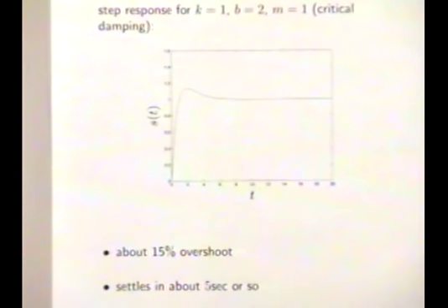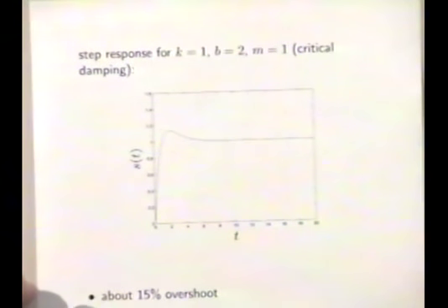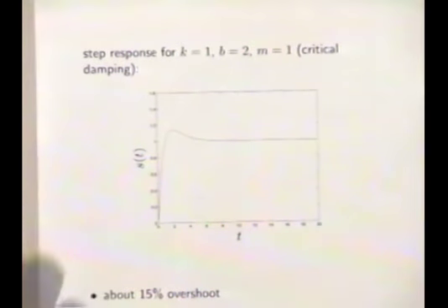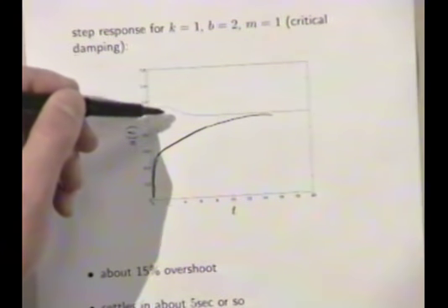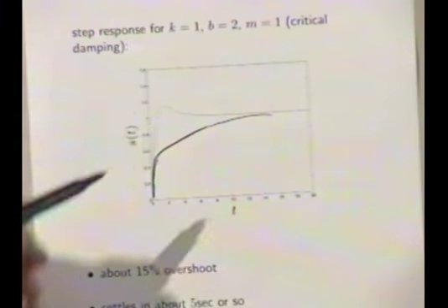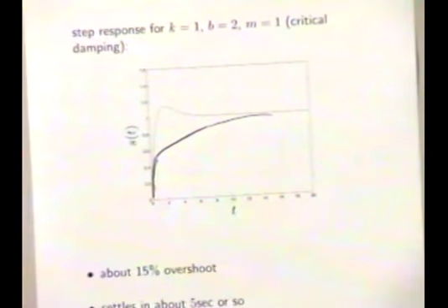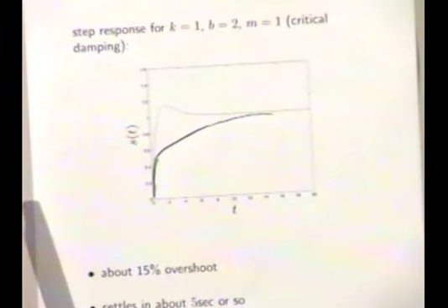If B were 10, if the thing becomes overdamped, what do you imagine the step response looks like then? Got 2 exponential terms. What do you think? Yeah, actually it would have a kind of a bump like that, a rapid bump, and then it would go like this, right? And in fact, if someone put a requirement that you don't overshoot at all, then you probably want something that's slightly overdamped. Okay? So it might look something like this and just take a long time to get there.